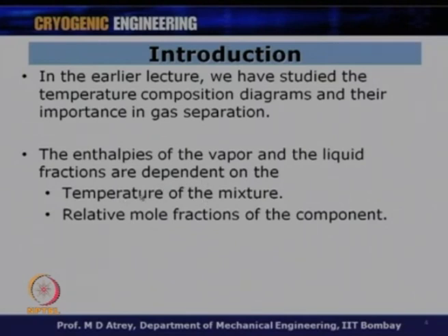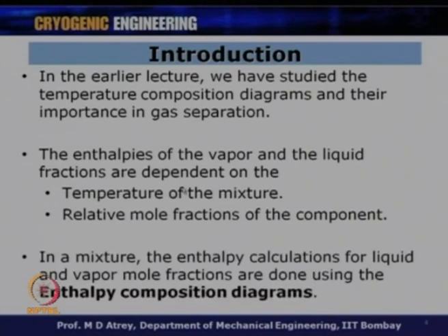It depends on the temperature and of course, the molar fractions of the components, that is the molar composition. These two parameters will decide, for a given pressure, the enthalpy of a given mixture. In a mixture, the enthalpy calculations for liquid and vapor mole fractions are done using the enthalpy composition diagram, and this is the importance of the enthalpy composition diagram.